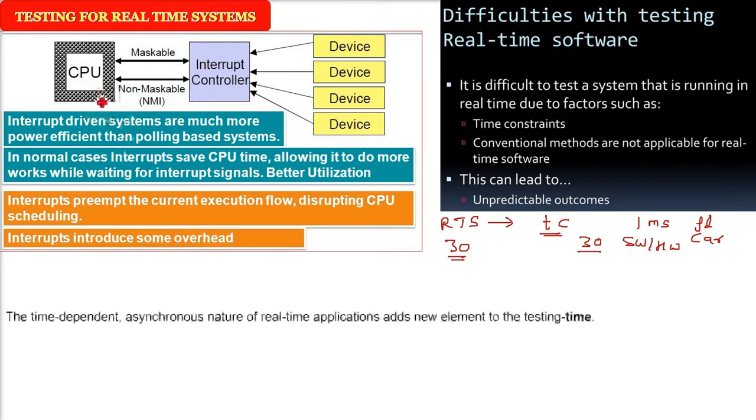These are interrupts. So the most important thing in a real-time system is the interrupt. Interrupts are those which want attention. They can be preemptive or non-preemptive. Sometimes interrupts are so important, like a trap, that they have to be accepted. Sometimes the real-time system may postpone attending to the interrupt. For example, the CPU will at certain times keep working and wait before acknowledging the interrupt. Otherwise, for some interrupts it has to acknowledge them by stopping its work.